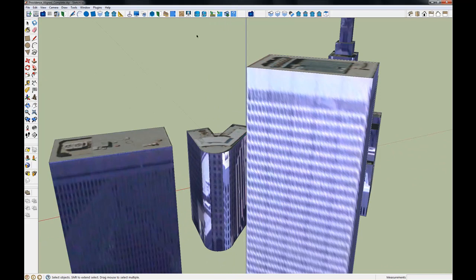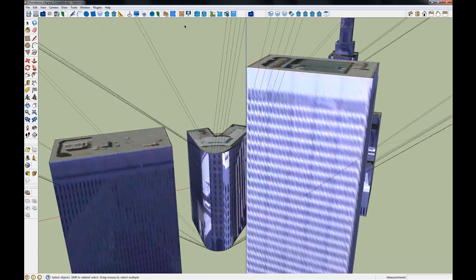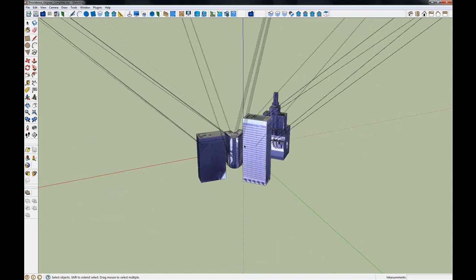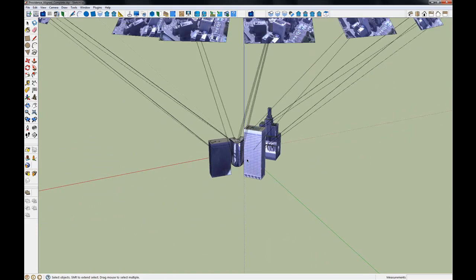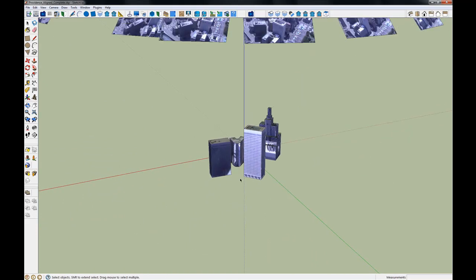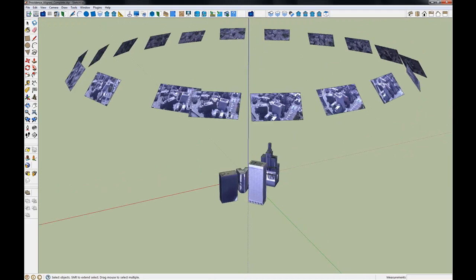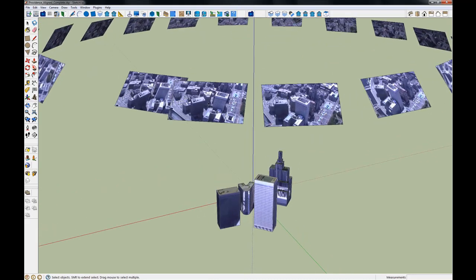If we select that face and use the show mapping tool, some of the faces are textured from over here, one from up here, several from over there. What we'd like to do is make sure that they're all textured from the same face. So again, I'll undo that show mapping, and I can see that curved wall from this view. So I'll select the curved surface, and then I'll hold down Control and also select the aux view that I want it to be textured from.